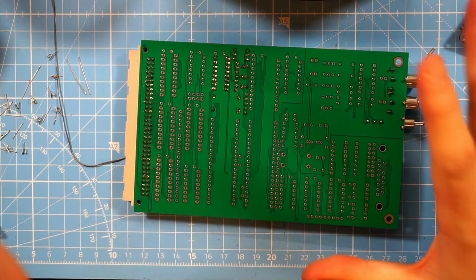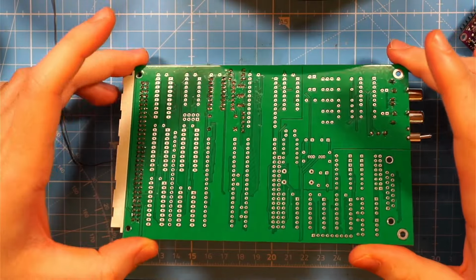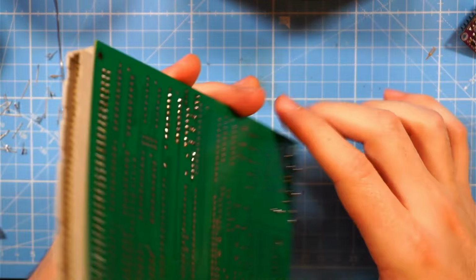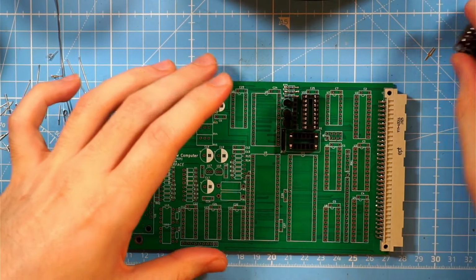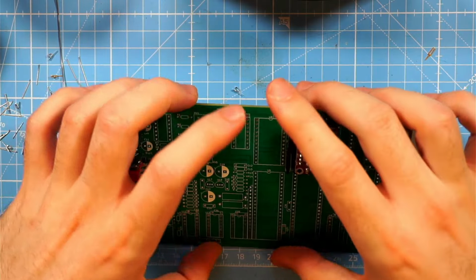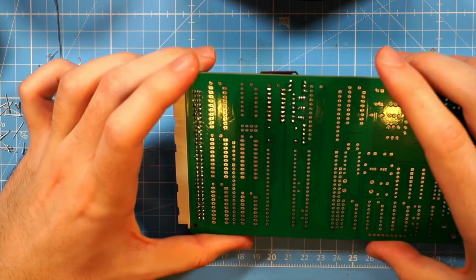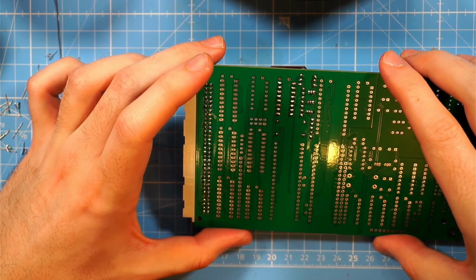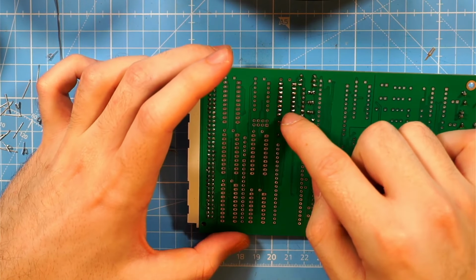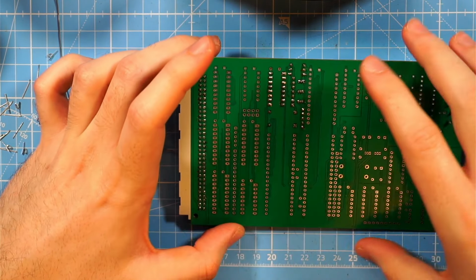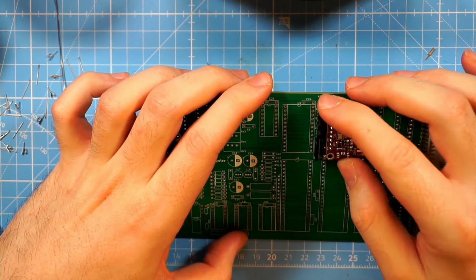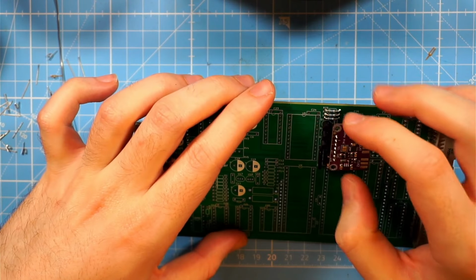Okay, I actually relocated the camera for you to be able to see what's going on a bit better. Those two sockets are soldered in. This means that I'm pretty good regarding this. So the next thing that I would need to do is to add the patch wires for the SCL and SDA pins for this clock generator right here, and then I'll use an Arduino to test it.